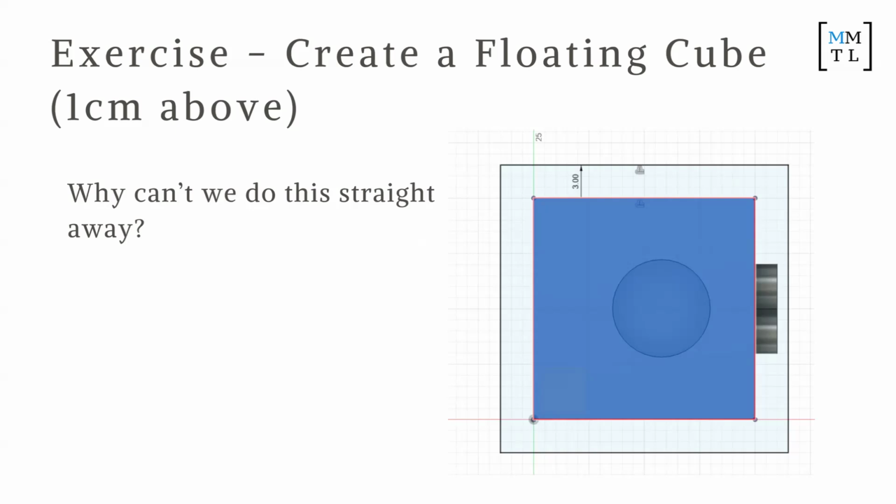And then now we just get, so you want to make it look great. 23 millimeters, yeah, because we're adding 3 to each edge. So if you accidentally did 26, just change it in your extrude, sorry, in your parameter.